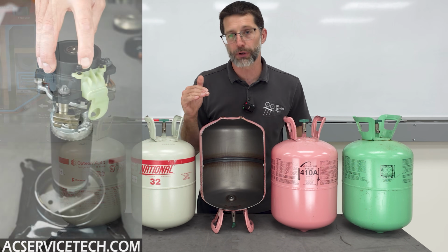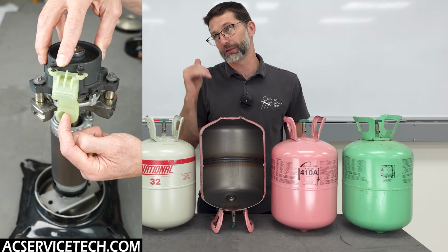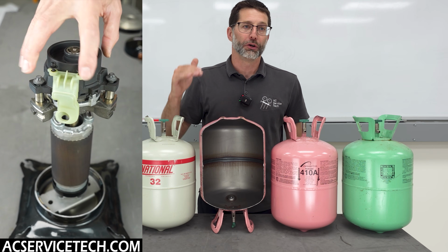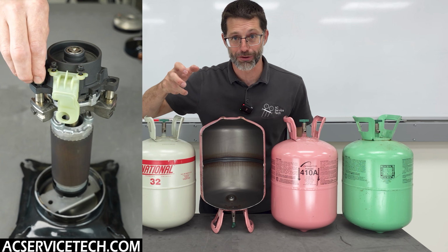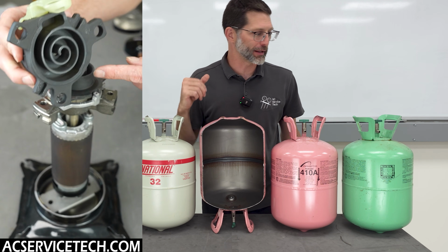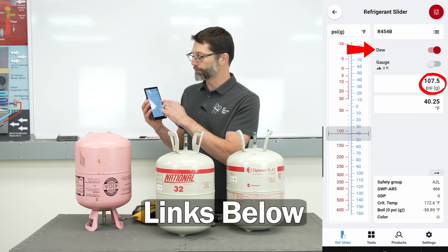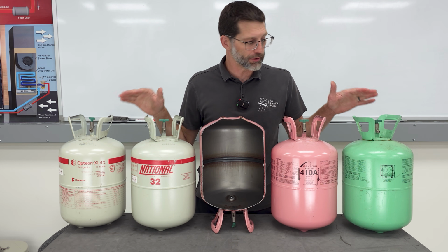Remember, the refrigerant compressor breathes vapor only. You should only have vapor entering it. If you ever have, say, liquid entering it, you're adding a non-compressible into a compressor, and you're also washing the oil away from the inside moving part. So that's not good.